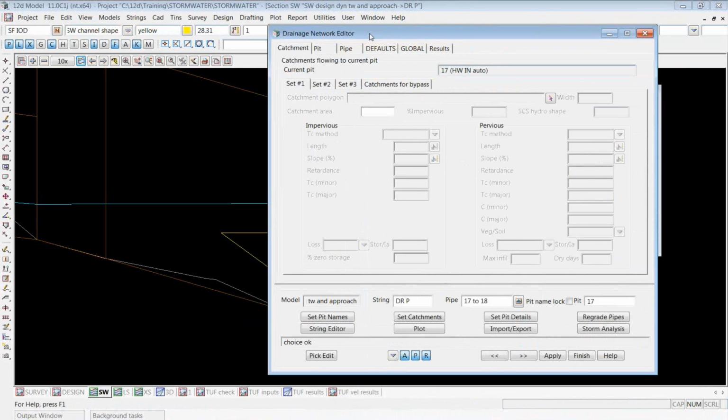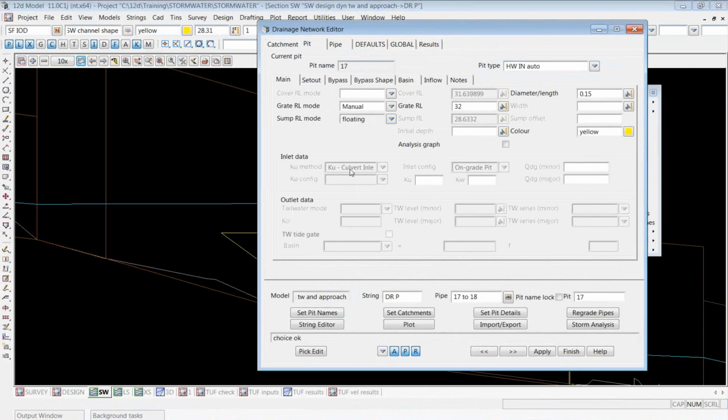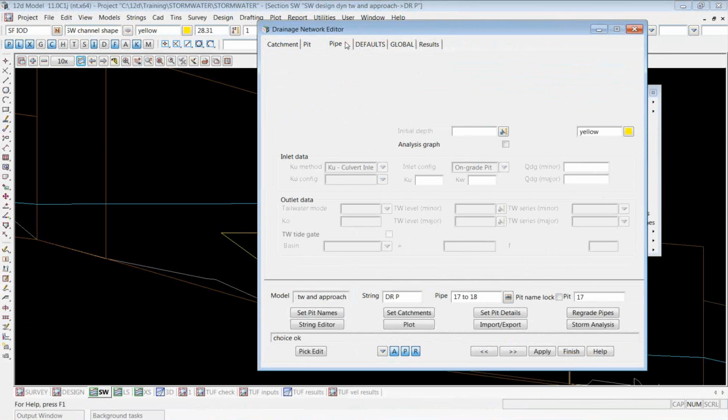And I go pick that. Okay, the first thing that happens is when we selected this head wall type, what that did is that went and selected the entrance energy loss coefficient and the exit energy loss coefficients. And they're constants, so no, we don't plot them.